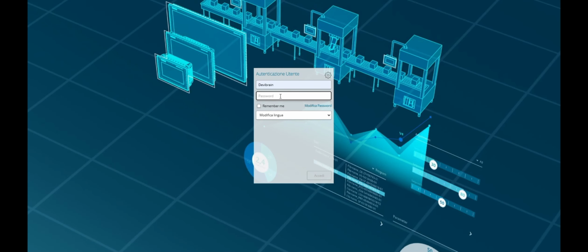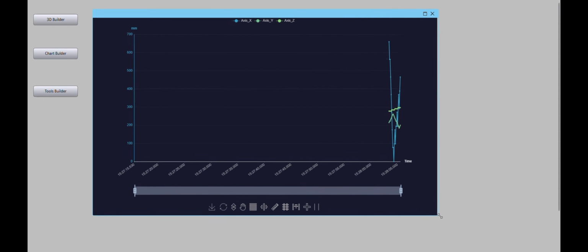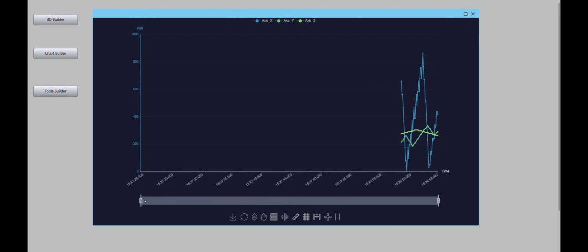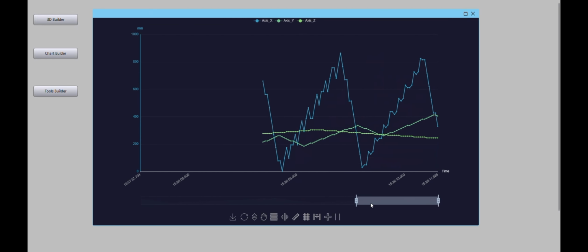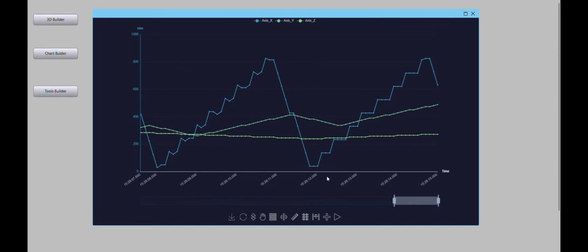Now let's log into the WinCC Unified runtime and see it actually live. We open the reference page on the panel. Inside the page, we can see that our chart is already active and acquiring data in real time. The values shown are different from those in the preview because these are the actual measurements being collected by the PLC. We can stop the chart at any moment to inspect the individual sample points using our tool.